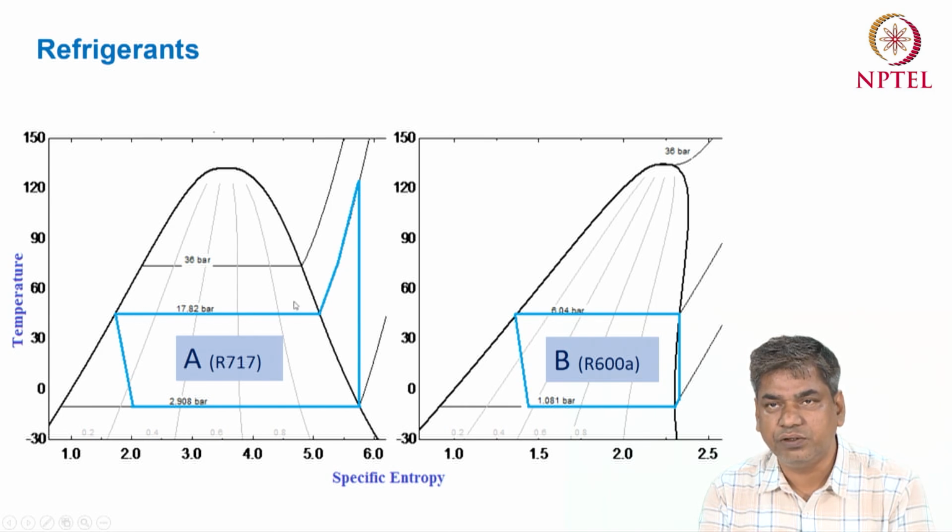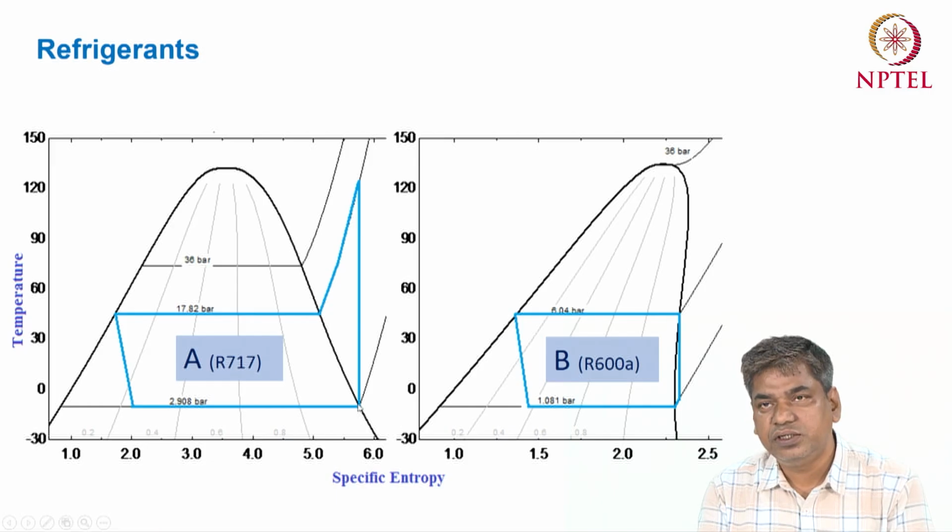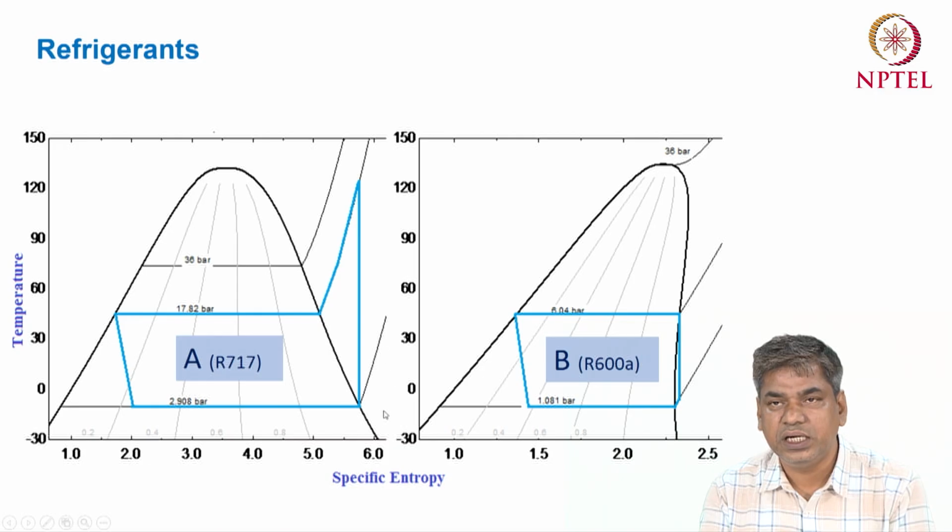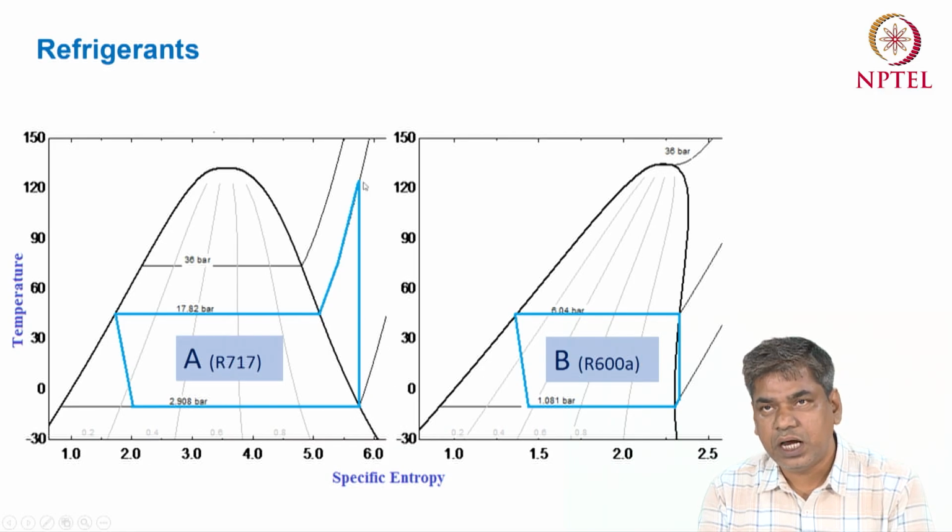Condenser pressure is constant for the condenser, so condensation or the heat ejection process is basically the isobaric process. So here you will see the compression process from the saturated condition to the superheated condition. If the inlet condition of the compressor is saturated vapor, then the outlet condition of the compressor should be the